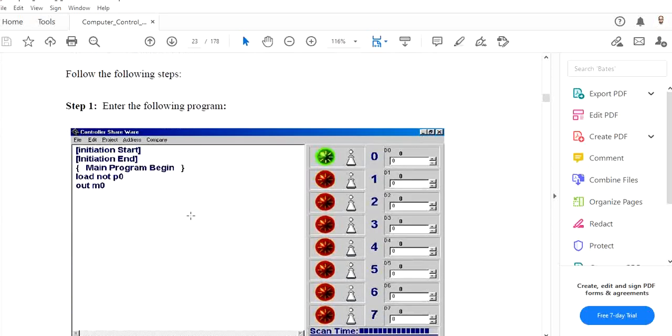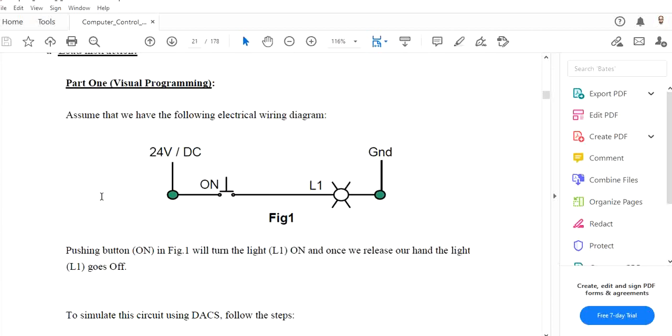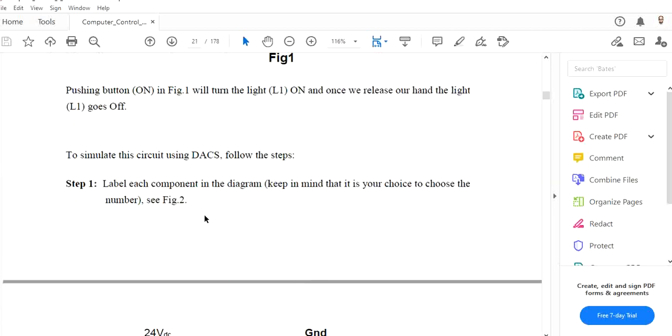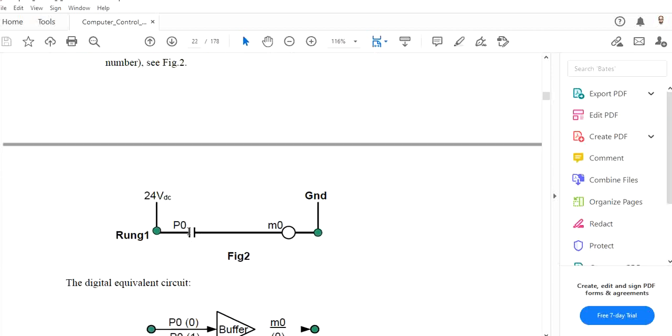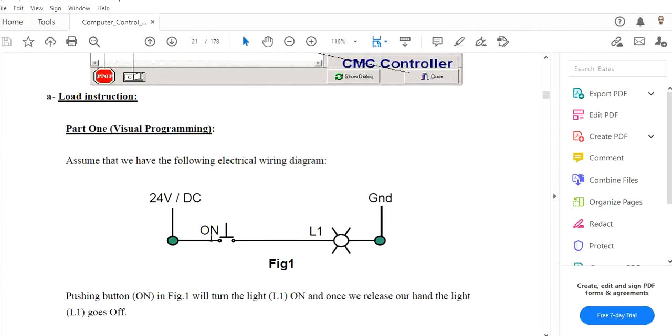So you can just fill all these things, is no problem. Similarly here, now this one situation is when you have a normally open push button. It can be normally closed as well. What is normally closed? If it is not pressed, if I say normally close, it means I make a normally close here. So if it is not pressed, it is on. When you press it, it will be open, right? This is how it works.